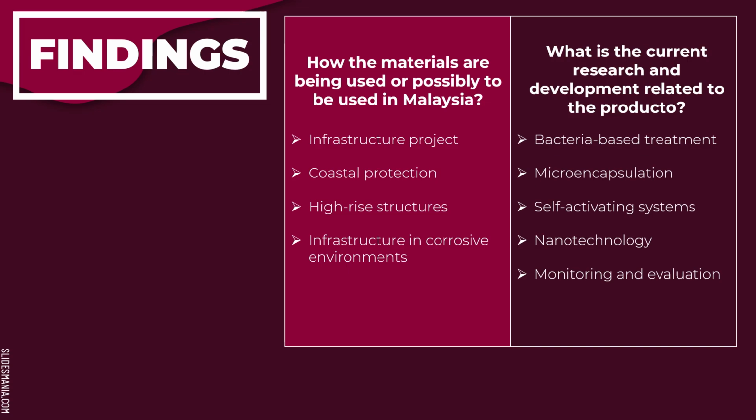Next, what is the current research and development related to self-healing concrete? Firstly is bacteria-based treatment. One method is adding certain bacteria to the concrete mix. When fractures appear, these bacteria become active and start producing calcium carbonate, which aids in sealing the crevices. Until cracks appear, these bacteria are inactive. Researchers are investigating various bacteria strains, enhancing their activation and survival, and enhancing the effectiveness of their therapeutic process.